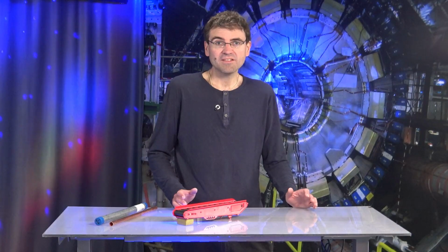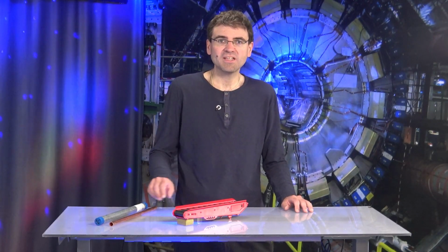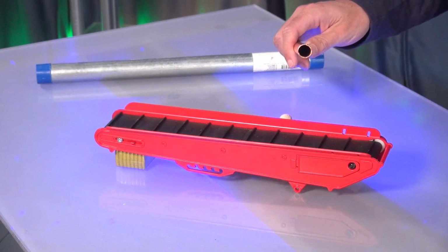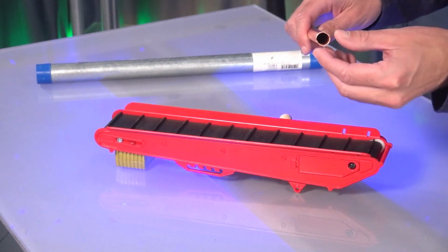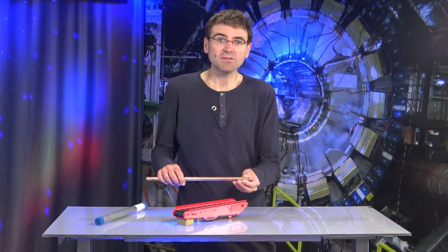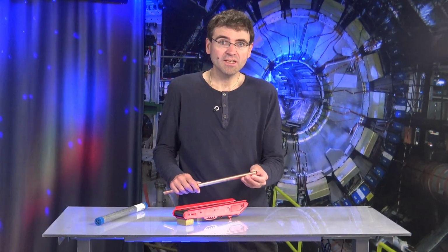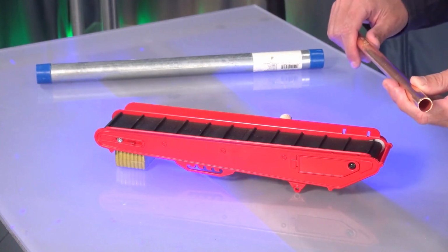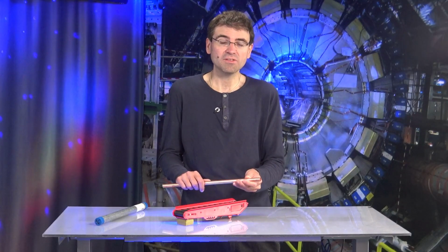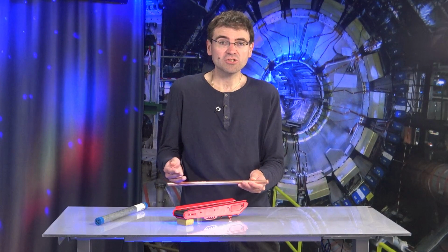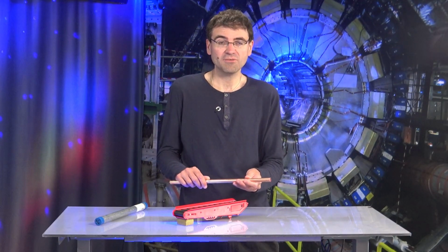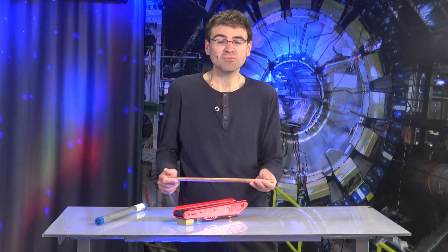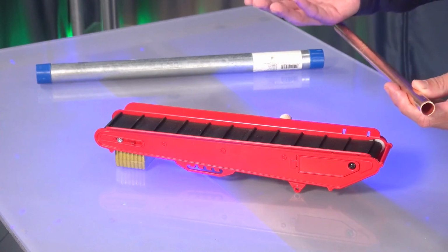This is a complex measurement technology, and therefore, we need to measure a number of variables. First of all, of course, we need to know the pipe diameter as well as the material thickness and the material the pipe is made of. Many pipes also have a coating on the inside. This also has a certain thickness and in most cases is made of a different material than the outside of the pipe. This also needs to be known because the ultrasound behaves differently in these materials. The same applies to the temperature of the liquid flowing through the pipe in order to obtain the most precise measurement possible. But how can we carry out this measurement?